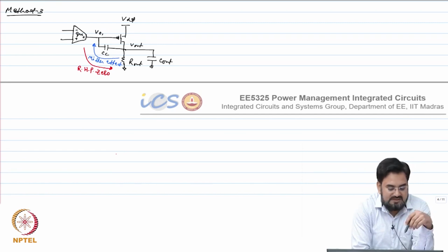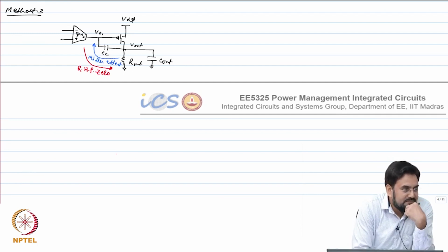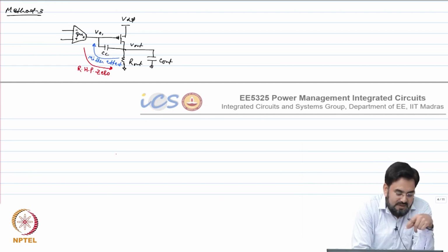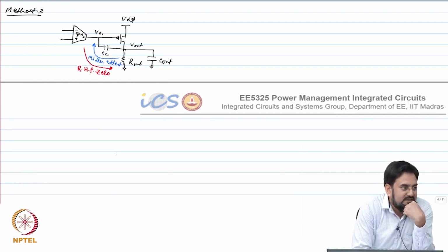I mean, you have two paths. One path is coming from the transistor GM, the other path is coming from the capacitor, and you want the GM path to be stronger than your resistive path, correct? So that's why you choose RC greater than 1 over GM. The higher the resistor, the weaker that path is. So your output will be mainly defined by your GM.